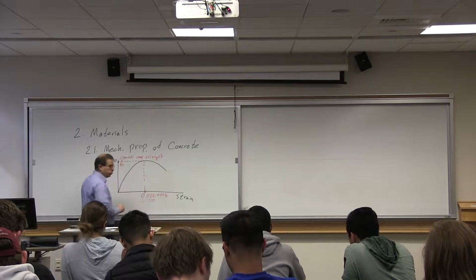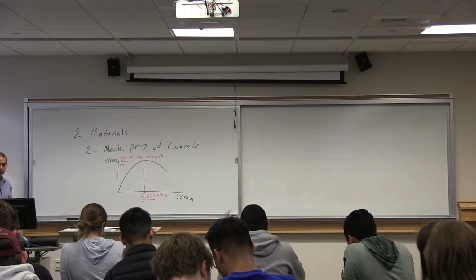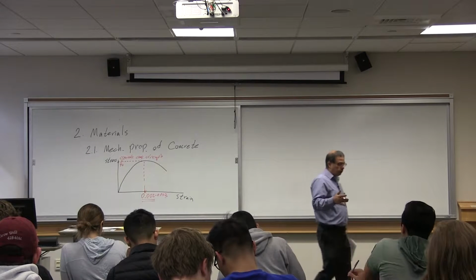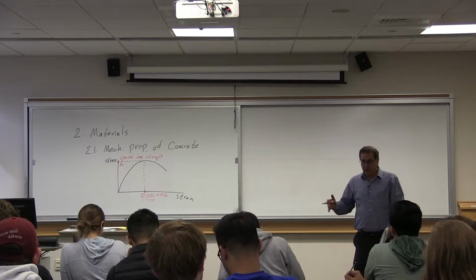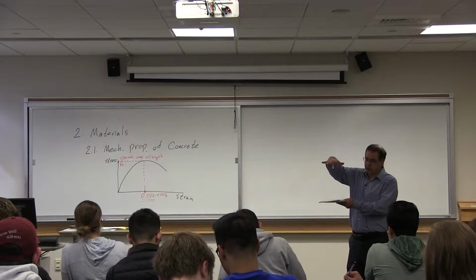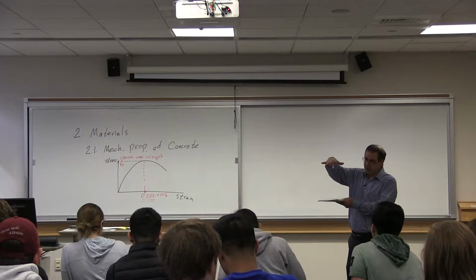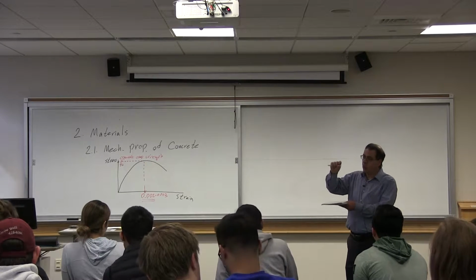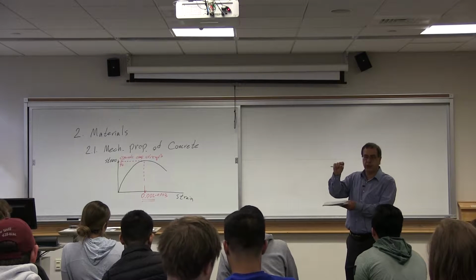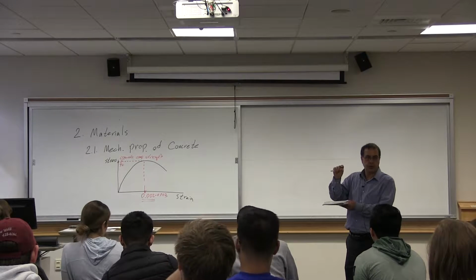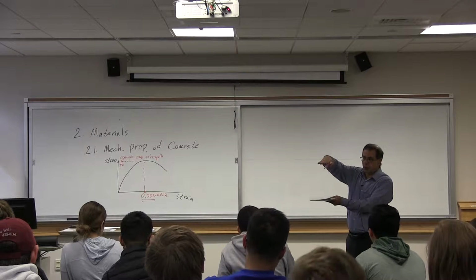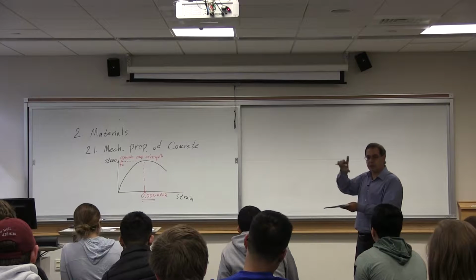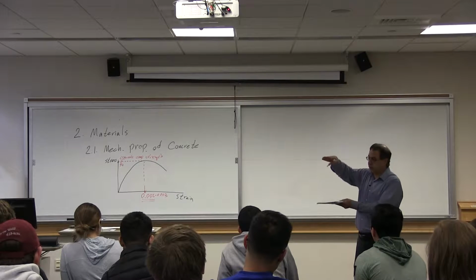We usually assume 0.002. 0.002, as you know, means that if you have a 10-inch tall concrete specimen and apply compression, at 0.02 inches it would crush. Imagine it is 10 inches tall, and you apply compression. 0.002 strain times 10 is 0.02, and it would crush.